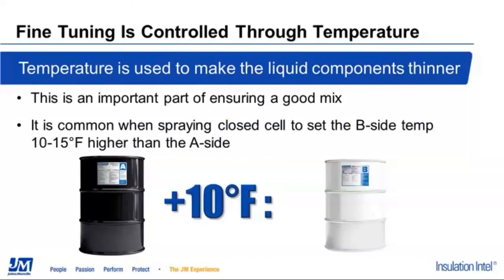We really want you guys to read the foam and pick the temperatures within that window that work the best for it. Wood's going to be different than steel. Steel's going to be different than concrete. Substrate, ambient temperature, all of these things play into what your processing temperature might be. And if you have to go outside of that window, we need a phone call before you do that.